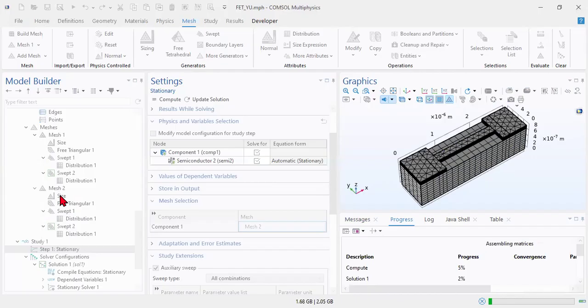So, when I just simulated, I showed there was some issue, right? COMSOL was showing some errors. So I told you that this error is actually for the mesh. If you select the wrong physics or something is wrong inside the materials, then you can find it easily, because when it shows errors, it will show you directly that this thing is wrong.